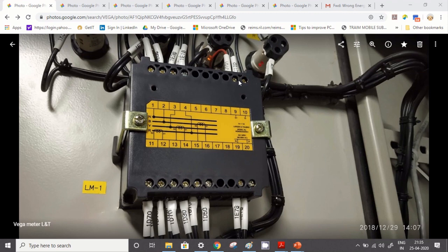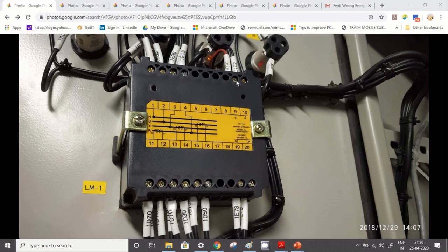After that, if data is still not coming, just for the sake of 1 minute, you have to interchange this connection, negative to positive and positive to negative. Reverse this connection here and see whether there is any change or not. After changing this, try to hard reset the SMPS controller once, and if you see anything coming there, I think then you have fixed the problem.